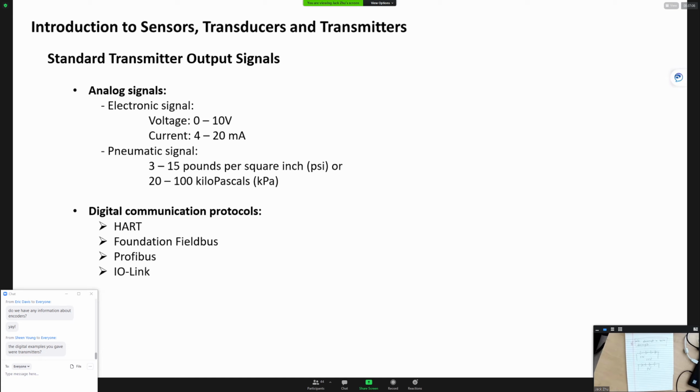When you wired them, each device had two wires. You put them in a loop: one wire in, then out to another wire, then out to another wire, then this wire comes back to here, make a splice, come back to here, make a splice, then go back. That's the old way of wiring those analog devices.